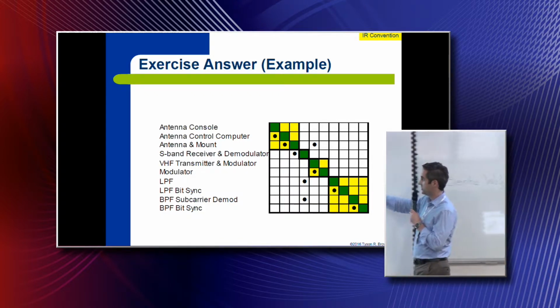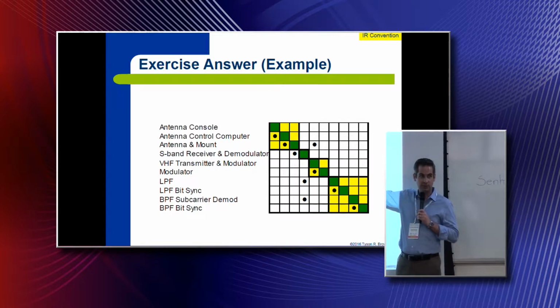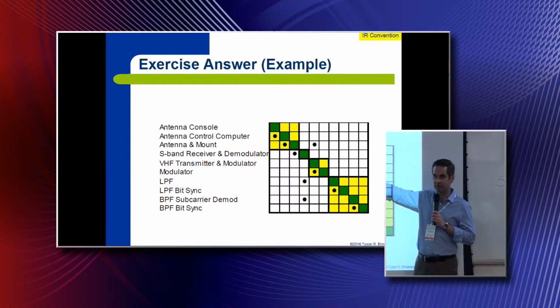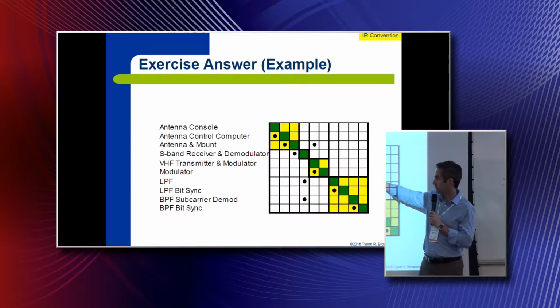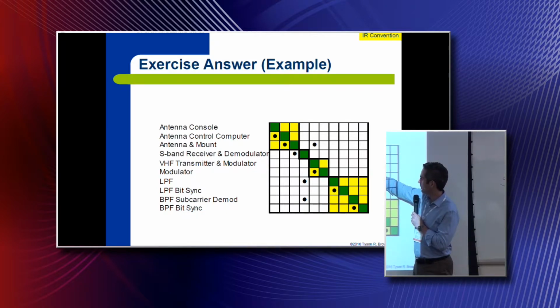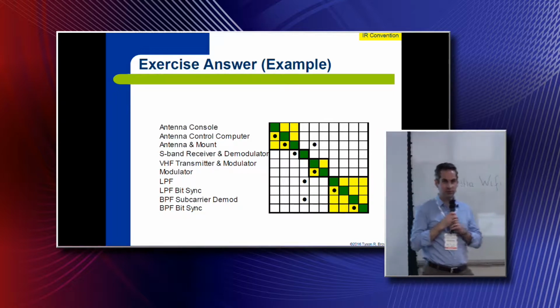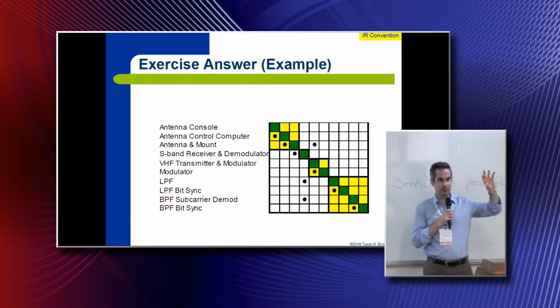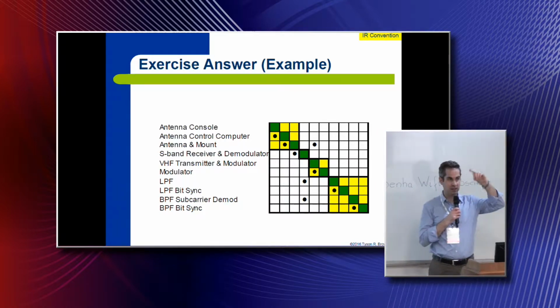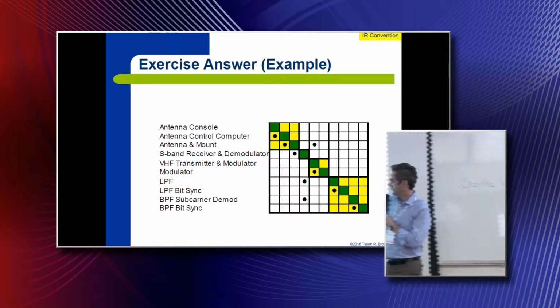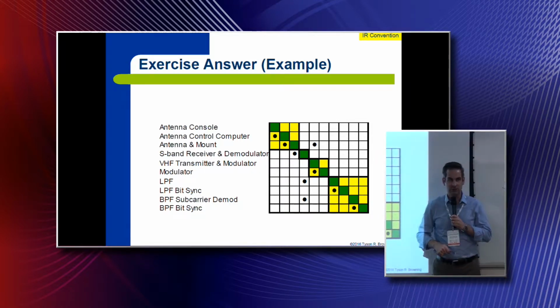Again, each dot here represents an arrow, and it's both an input and an output, depending on your point of view, right? So it's an output from one and an input to another. So as long as you have arrowheads in your block diagram telling you the direction of the relationship, you should be able to decide if it's below or above the diagonal in the DSM.